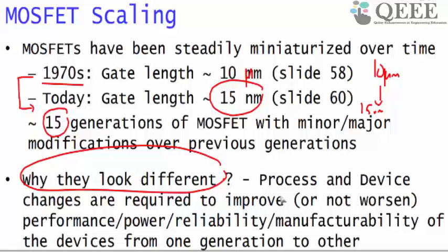Your drive current may not be good. Your off current may be large, and also your transistor may fail very easily. So you need to look at all these things. You are not doing scaling for the sake of scaling.